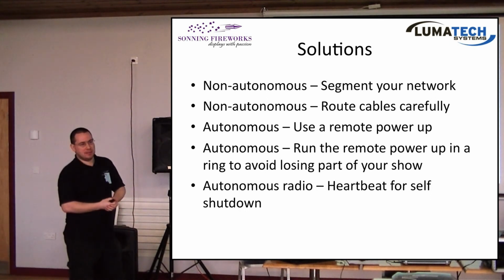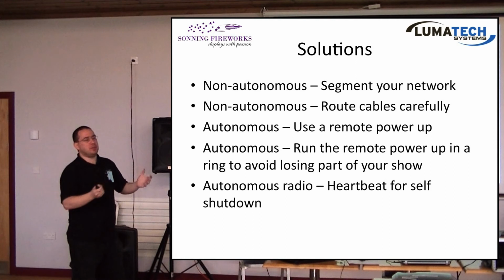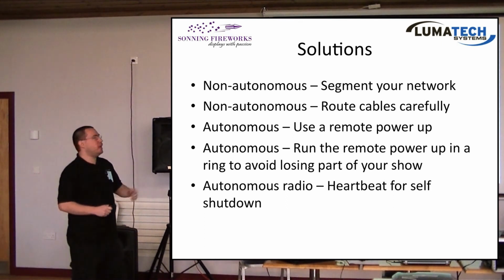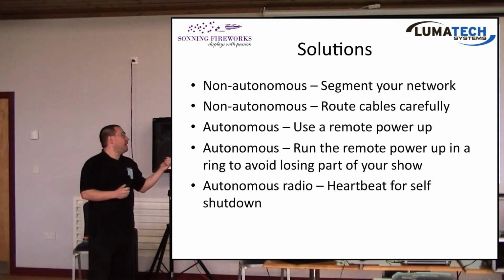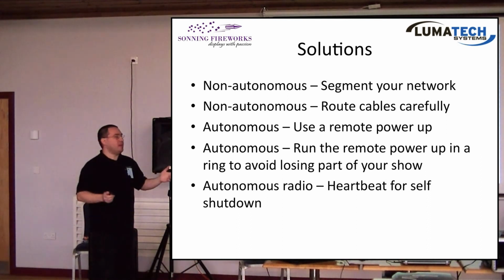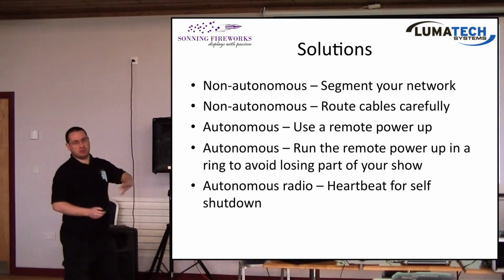Are you able to relay data as well? It depends on the protocol, the network, but RS485 is specifically designed to be a bus. So you shouldn't really, you can get noise and other issues if you try and run it in a loop. RS485 is quite resilient, but the standards say you shouldn't run it in a loop. So the way we do it, we have 2 chances. If we blow one cable, all the modules will stay on; if we blew another cable, then the modules between there would switch off. So that's how we get around this issue of having an autonomous box run away with itself.